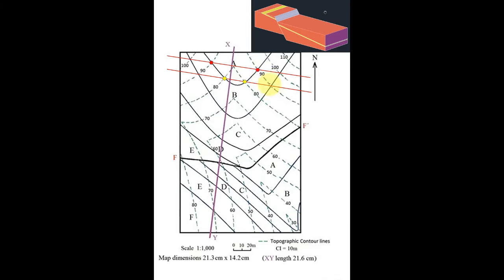By these two strike lines, I now know what is the distance between them. And the property of the strike lines is such that the other strike lines will also be at the same distance for the same inclination. Since this upper part is going to have almost the same inclination, the strike lines are also going to be equidistant to each other, right? Then let us see if there is anything else on this AB junction.